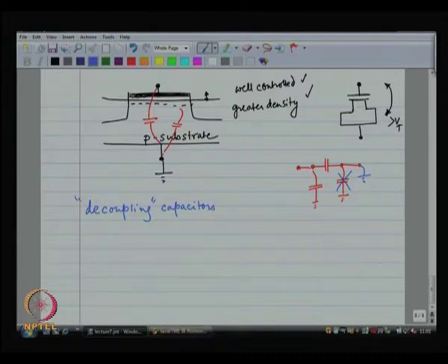We usually make a lot of decoupling capacitors where we want a large capacitance value, therefore we want great density, because we do not want to waste huge amounts of area. We also want, in a decoupling capacitor, one side of the capacitor to be either ground or a constant fixed potential. In small signal, the fixed potential is ground. So this kind of a capacitor is advantageous.